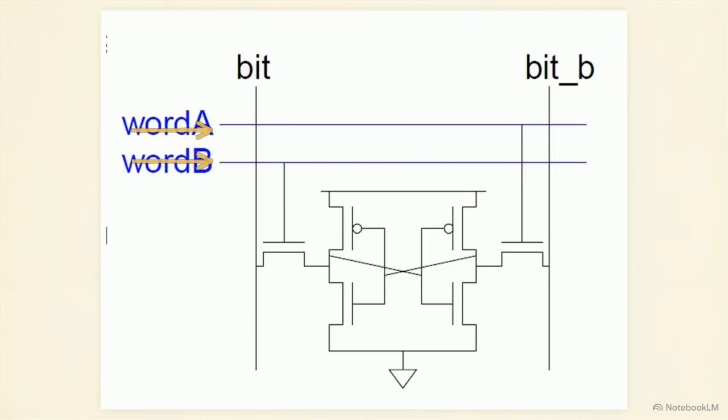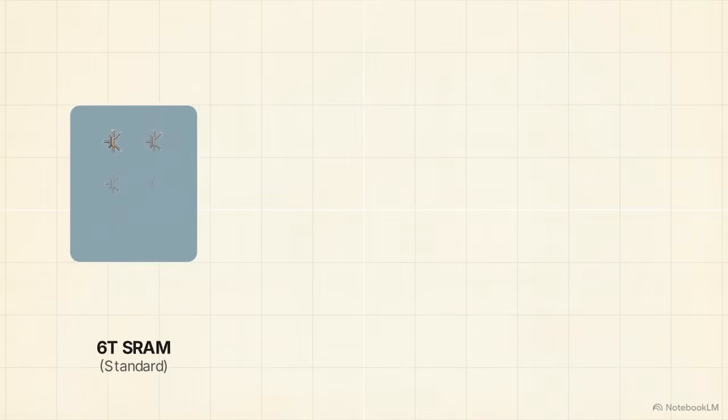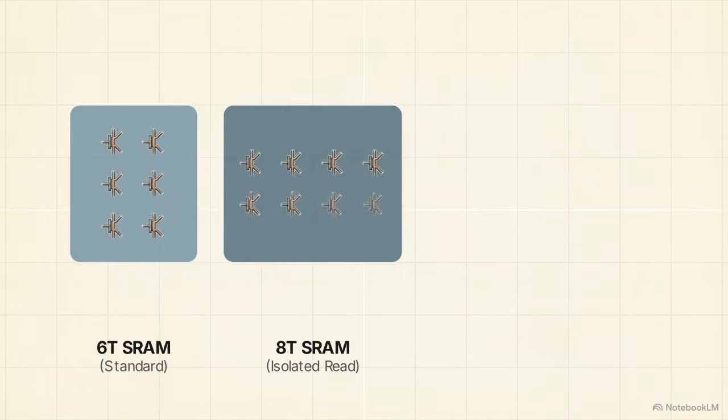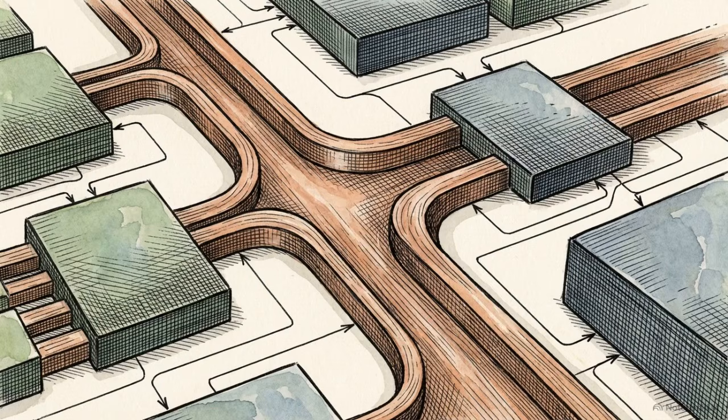This diagram outlines a dual-ported cell, utilizing two independent word lines and bit lines. This topology allows the system to execute two independent single-ended reads simultaneously, or utilize time multiplexing to read and write on alternating clock phases. The physical trade-off is geographic. Adding more access transistors significantly increases the required silicon area per bit. Multi-ported arrays deprioritize overall density. They dedicate premium silicon real estate purely to moving data out faster while maintaining absolute read stability.